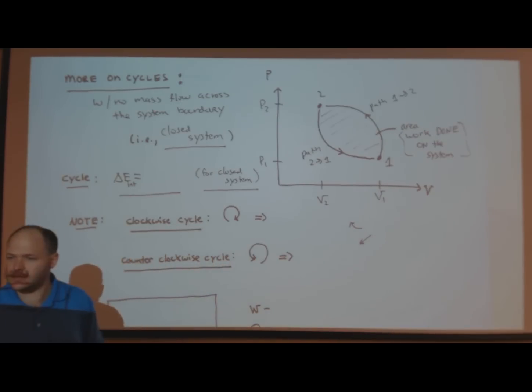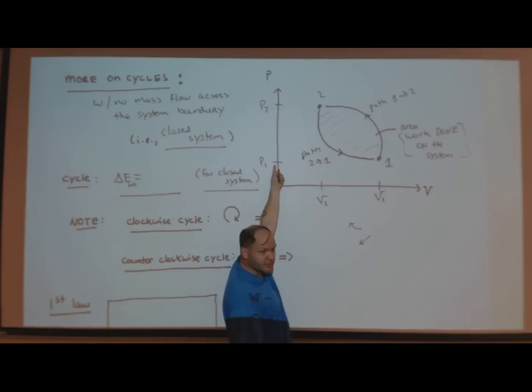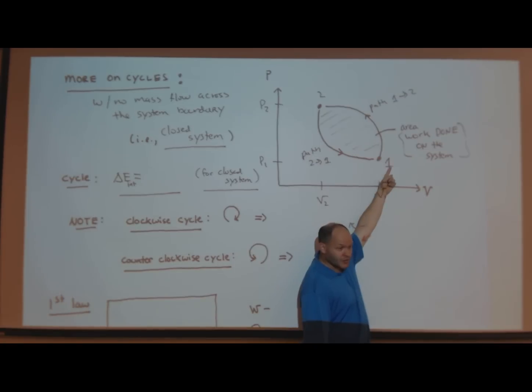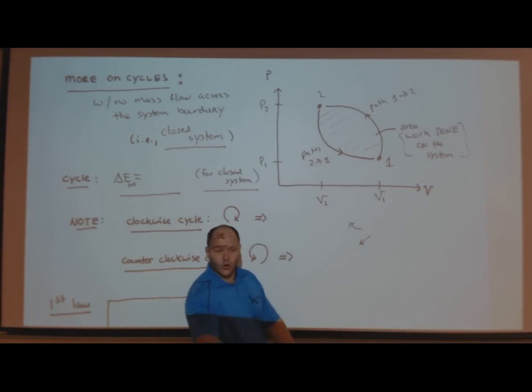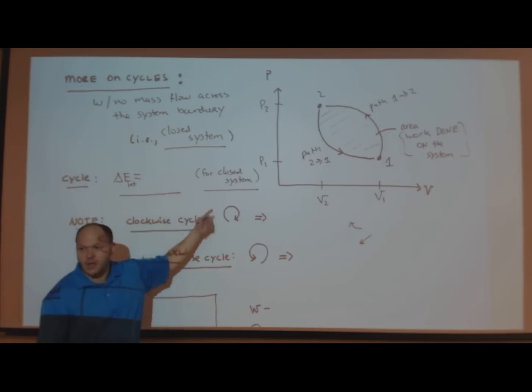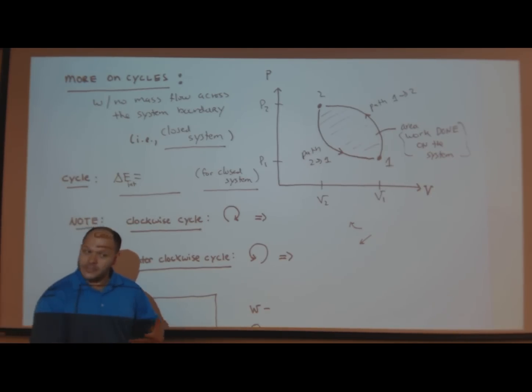How do we define it? If I'm saying this is a state, it's defined by the temperature and pressure. So if this is a state, the temperature, there's a T1. If I go a cycle, I go right back to the same temperature and pressure, closed system, I didn't add any new mass. And if I'm at the same temperature and pressure, the internal energy is right back to where it was. Now, if I have an open system,